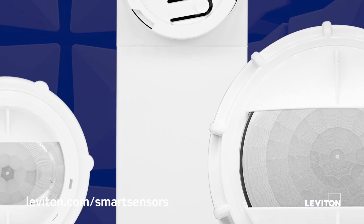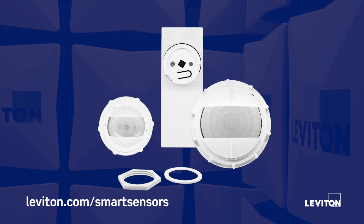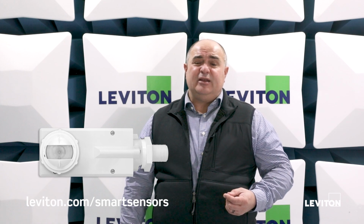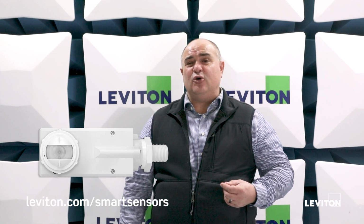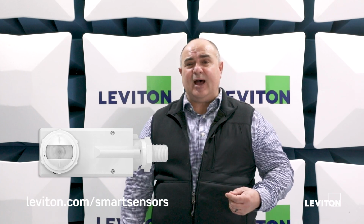Now you say, well, what's the deal on that? Well, we have a fixture mounted solution where the sensor is mounted within the fixture, as well as the exact same device that can be mounted on the 1/2 inch knockout of a given junction box or a given fixture. And these will come with lenses that not only work at the lower levels, say a medium range for 8 to 20 feet, but all the way up to 40 feet, another lens, as well as the aisle masks. And these allow you to maintain the full code requirements utilizing that exact same smart sensor app.